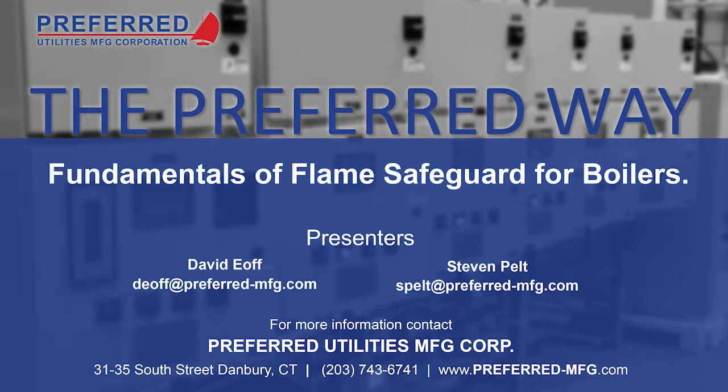Would O2 trim catch an over-rich condition that you were discussing from someone limiting the air into the boiler room? That's a great question, because yes, most parallel positioning or any air-fuel ratio type control devices that incorporate O2 trim will allow you to put in max and min values and either alarm or shut down. It becomes more than just a device that keeps you right on your air fuel ratio curve, regardless of the ambient conditions, but it also would prevent a super rich condition.